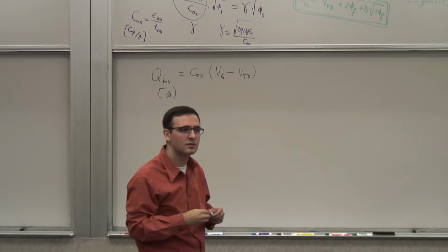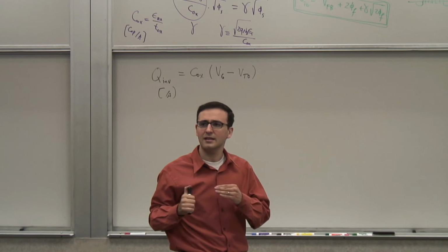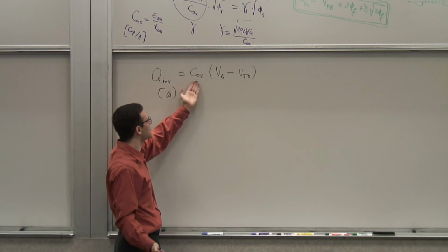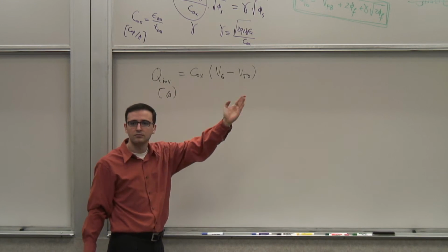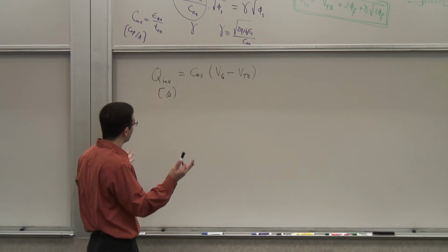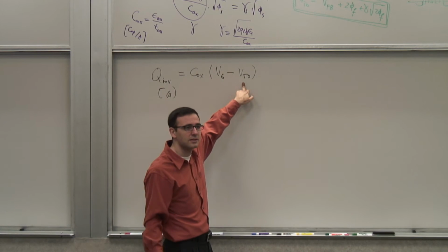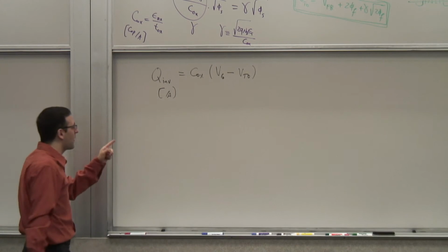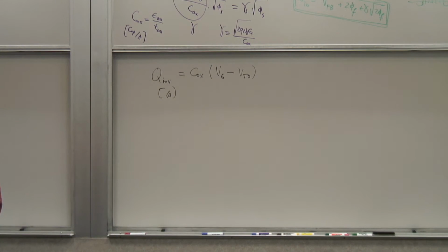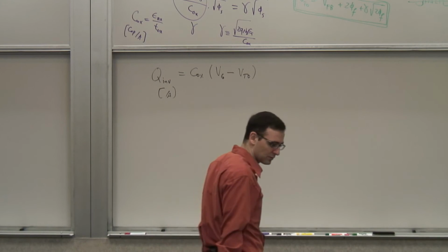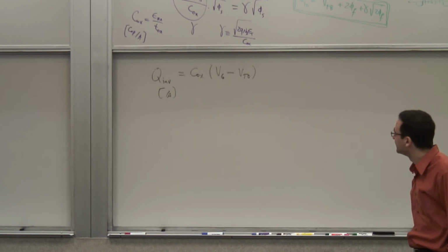Does that make sense? So I'm saying that any voltage in excess of Vt0 will induce additional charges, which is basically a capacitance charge. It's a Q = CV. So this is a very important expression. It's very simple right now the way it is because I've lumped everything into this Vt0. Okay? And we'll see why we use the zero here, because when we go to the MOSFET, the actual transistor, then you'll see how it can change through the substrate voltage, basically.